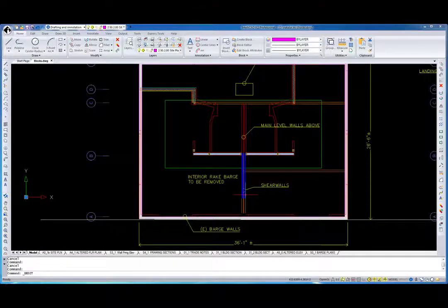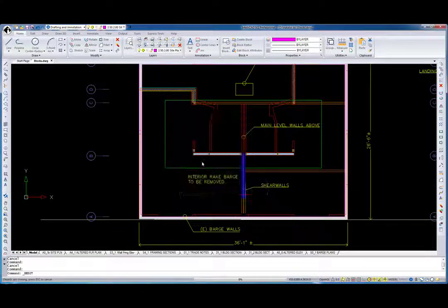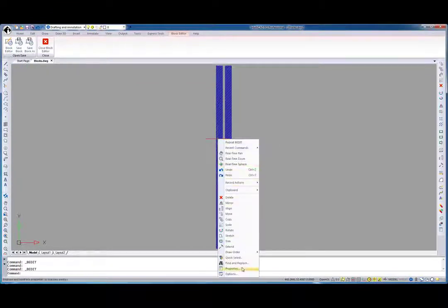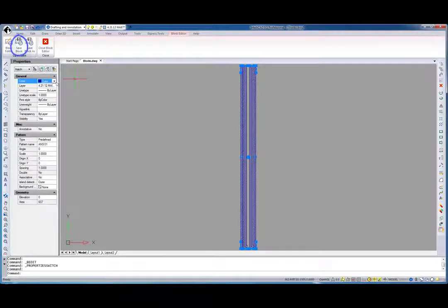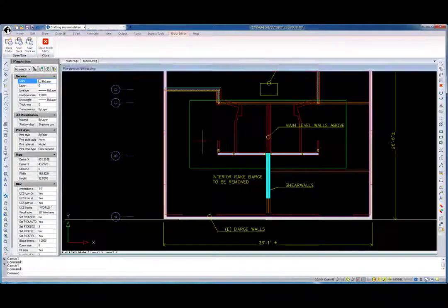Double-click on a block in IntelliCAD 9.1 to open the new Edit Block Definition dialog box, where you can select a block that you would like to edit and switch to the block editor. You can select different blocks by pressing the Block Editor button. When editing is done, you can save modifications to the block with its original name or a different name. To close the block editor, press the Close Block Editor button.